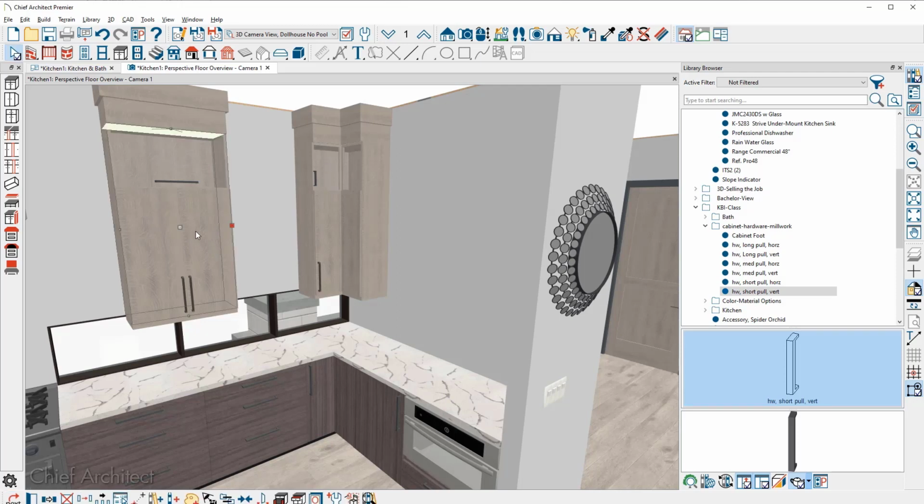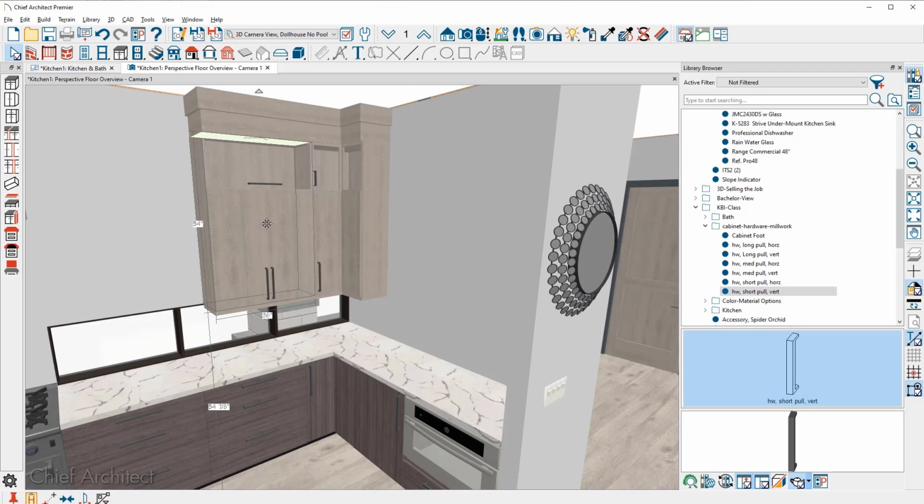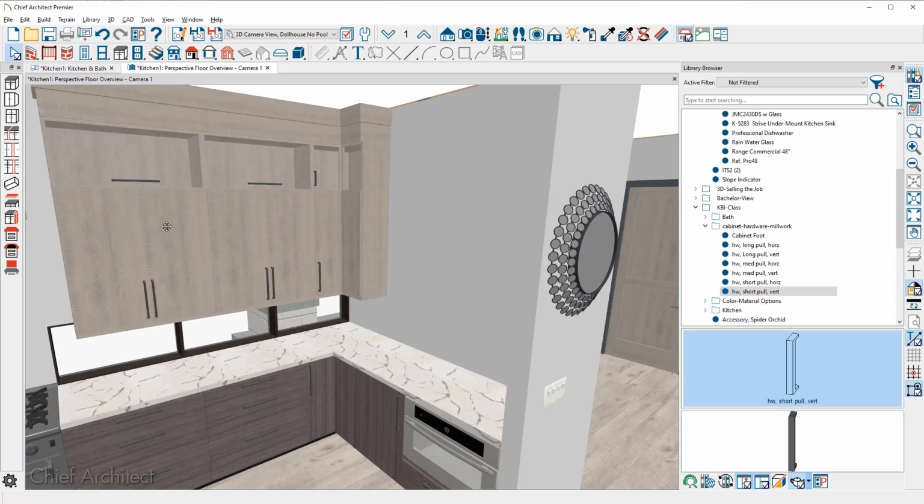I'm going to click on the cabinet, and I'm just going to slide that over and bump it to the corner cabinet, and then let's resize that. I'm going to go ahead and adjust it. You see how it pops out with the dimensions 36 inches. Make a copy of that cabinet. Use the copy tool in the lower edit menu. Slide a copy of this over, and then what I like to do after I've slid it over, let's go ahead and bump it. Cabinets bump, and then I have a contiguous run of cabinets.